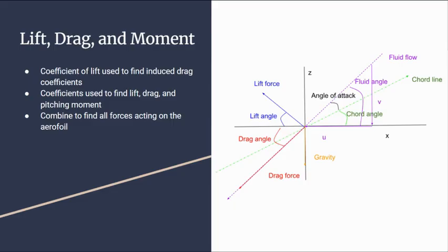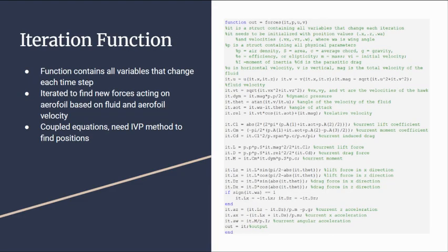The model becomes a system of coupled ODEs because the force depends on the wing's XZ position, its velocity, and its angle of attack. These interactions mean there's no realistic closed-form solution, and multi-step methods don't help much because the future flow conditions may change from step to step.